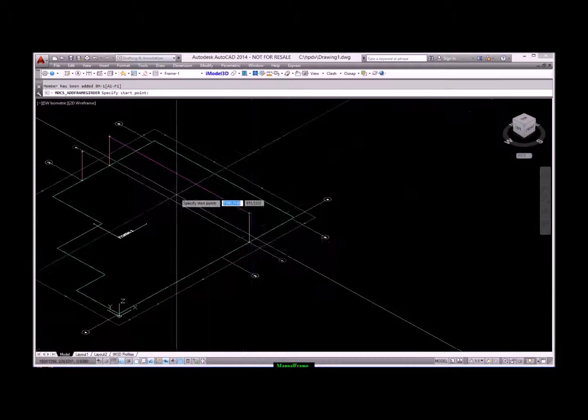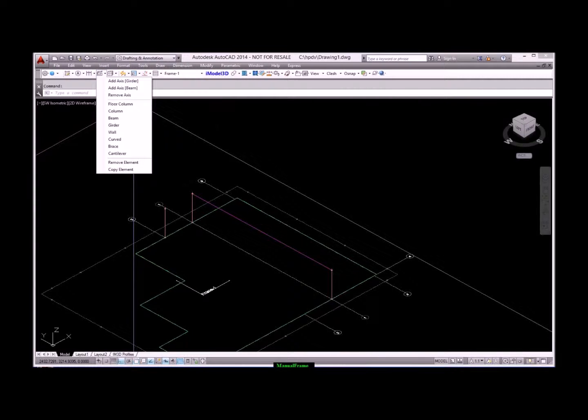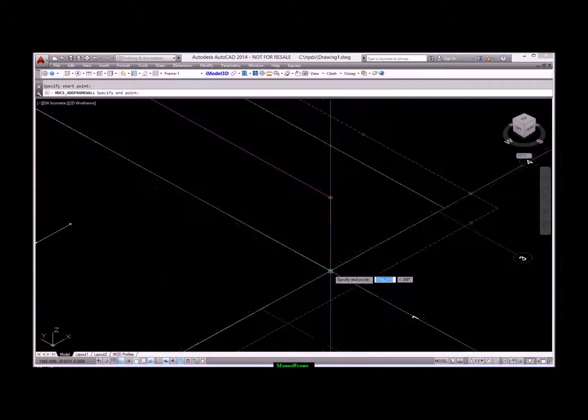Curved. Allows you to draw a curved beam and wall simultaneously. You will be asked to specify the curved 3 points. A beam and a wall element will be drawn separated by the slab thickness value.